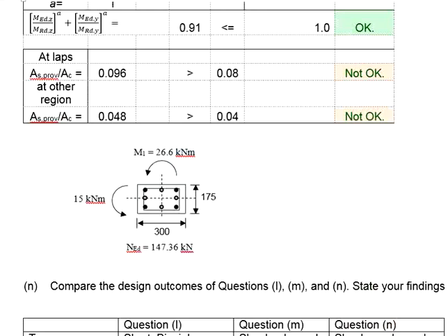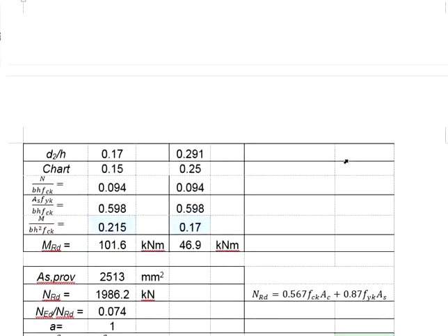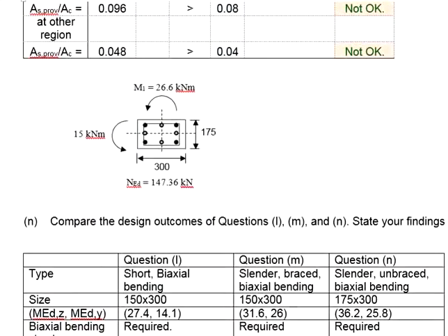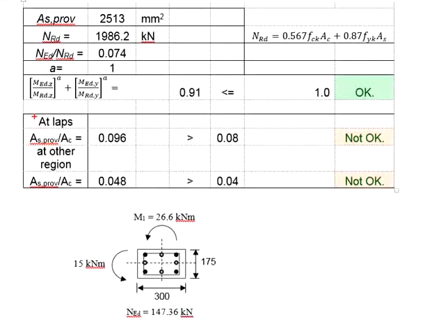Particularly for this case, reducing the amount of reinforcement is not workable. Reducing the reinforcement bar to be less than the maximum limit will eventually lead to the failure of this equation. This leaves you the only solution, which is to enlarge the column section.